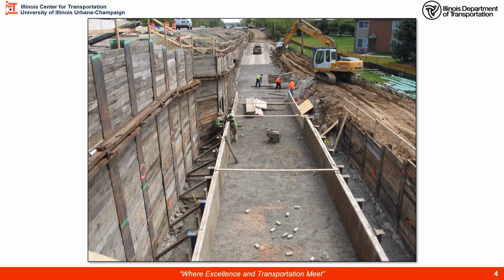Here is a foundation being prepared for a mechanically stabilized wall, MSE wall. Notice that there has been some excavation beyond the footing. This would be the formwork for the footing, which would rest in here, the other side of the formwork. And it appears to be a little bit more than 2 feet, but according to our specification, we would only pay for 2 feet beyond the edge of the footing.